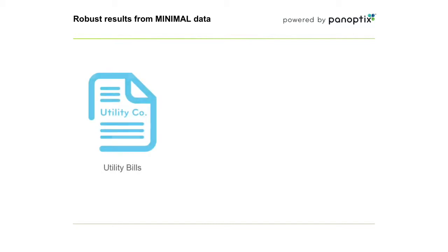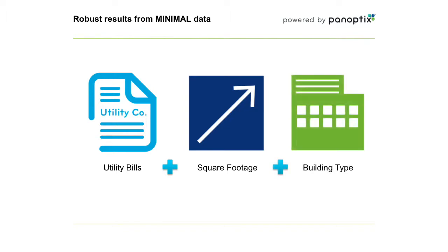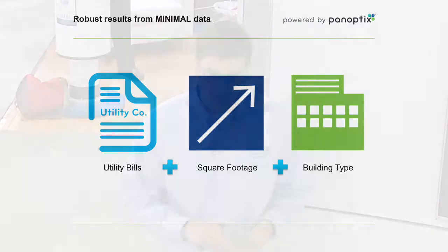One of the key components and fundamental tenets around Lean Energy Analysis was to use as little data as possible to inform building owners and to use data that's readily available. So one of the key components about Lean is the minimal data that's required. And you can see it here. It's utility bills. We can do it with as little as 1 year, but we prefer 2 to 3 years for increased resolution. Square footage of the facility, and then the building type. So building type is medical office building, a hospital, a dormitory, public school, something like that.